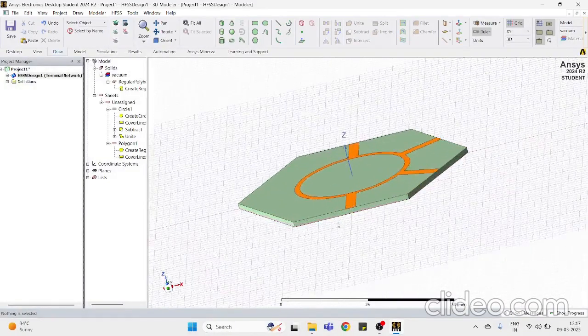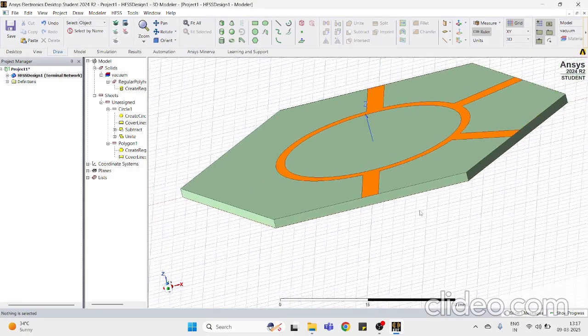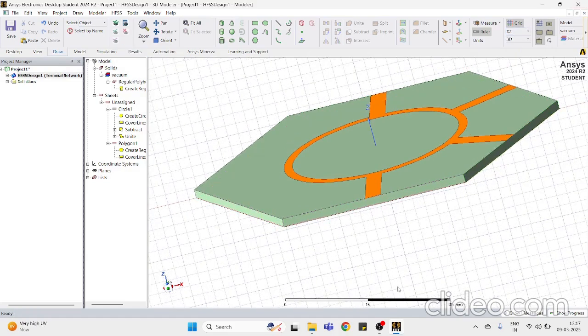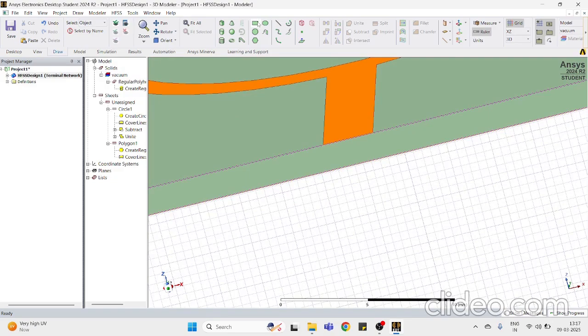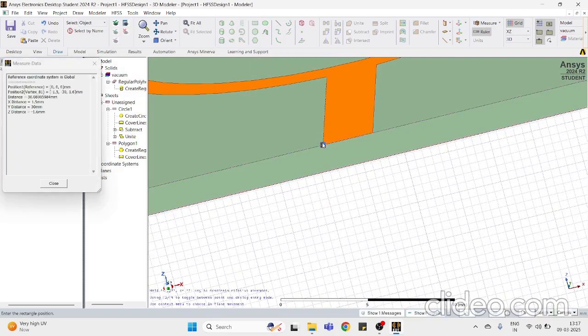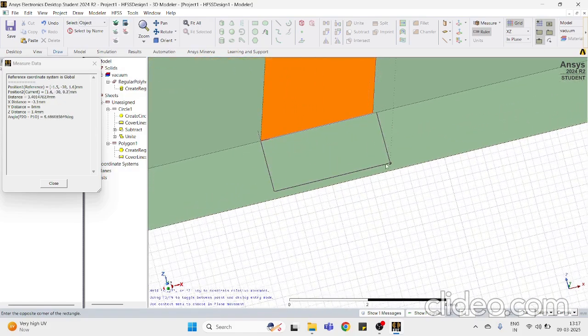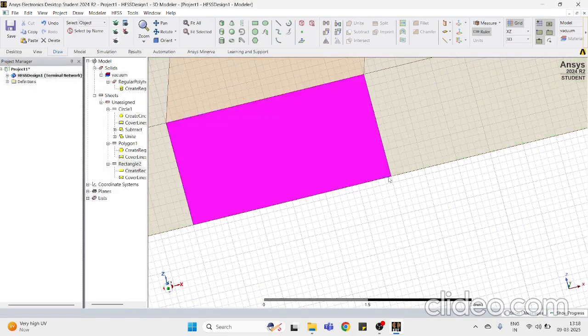And ports, as I said, rather than the geometry, the more easier way to do it is just visual way. Just a visual way is very efficient. So I'll just change the axis to XZ axis now. As mentioned before in Microstrip line, I have explained it properly why this XZ needs to be selected, and I'll start drawing a rectangle. Starting from this point, you see a small rectangle, and properly align it over here. Zoom in as much as you want, and then now you can see the port is properly aligned. So just drop it here.